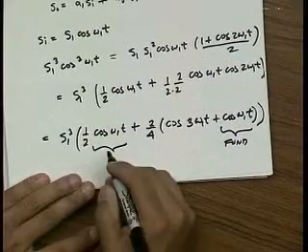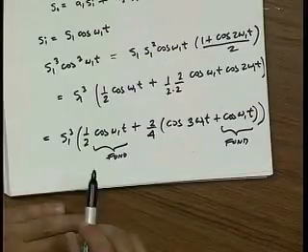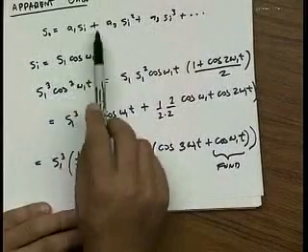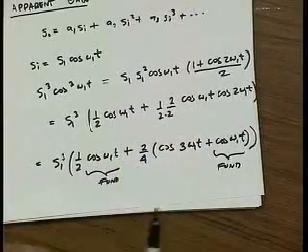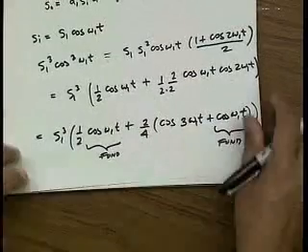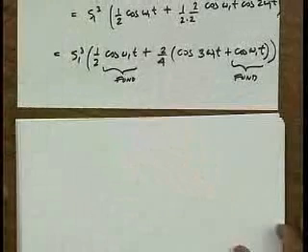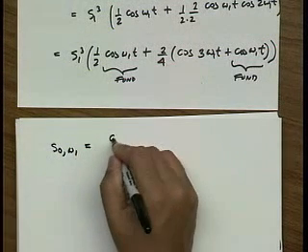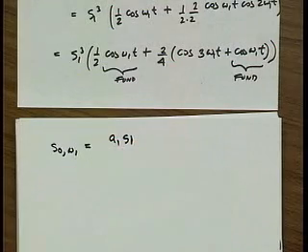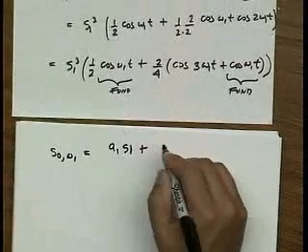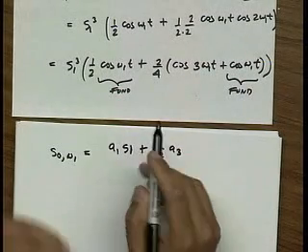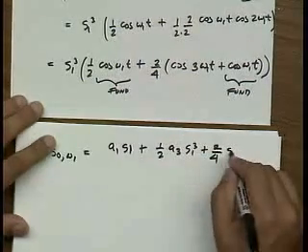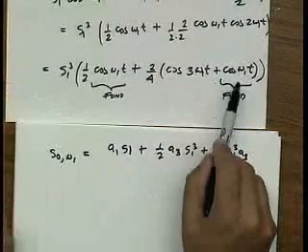And so we see that the cubic operation generates two fundamental signals, and depending on the sign of A3 in this expansion, these fundamental tones could either add to the linear gain term or they could subtract. For a compressive nonlinearity, they do subtract. So let's collect these terms. I could say that my output signal at frequency omega 1 is equal to A1 times the input amplitude, which we're calling S1, and now I have two more amplitudes: 1/2 A3 S1 cubed plus 2/4 S1 cubed A3, which is the second term here.